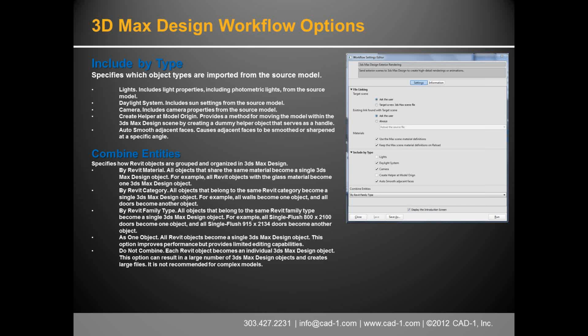All right, so we've got the daylighting system. If you're going in and setting up your site with the sun, importing all your site material, and we want to do a solar analysis, it'd be good to bring that in, because I've already set that all up in 3ds Max. I want to bring that over. The next part is the cameras. If you've got the different cameras in here, you can bring those over, although I haven't had great success with that every single time, but we'll give it a shot today.